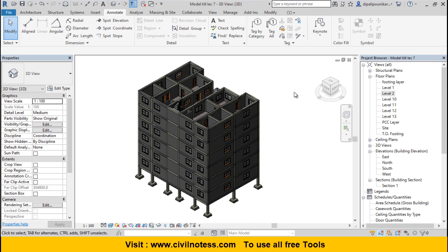So guys, this particular video helps you take the quantity and, with the help of the rate analysis, estimate the total cost of a building, including how much labor is required and how much material is required, which you can easily identify. This video is very important for all civil engineers who work at site, who work in consultancy, who want to start their own work, and for civil engineer freshers. Or you can take this data for your final year projects also.